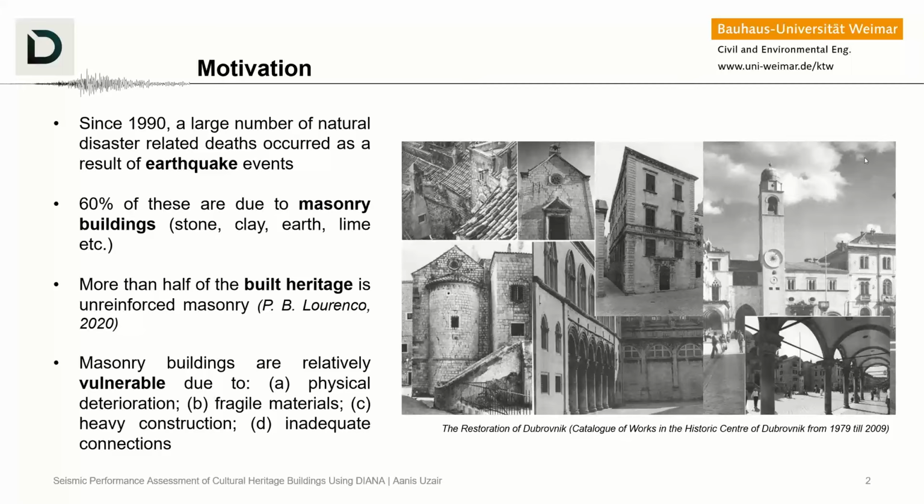This makes the structure extremely weak in terms of strength to lateral motions, where the structures exhibit very low tensile capacity. The cracking response is very brittle, and the structure shows very limited ductility in the nonlinear range.